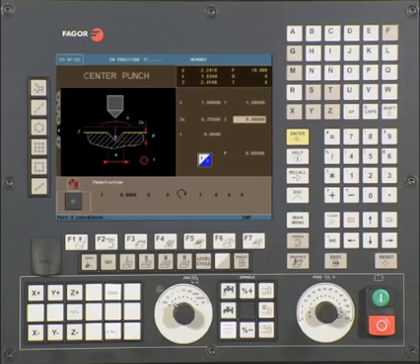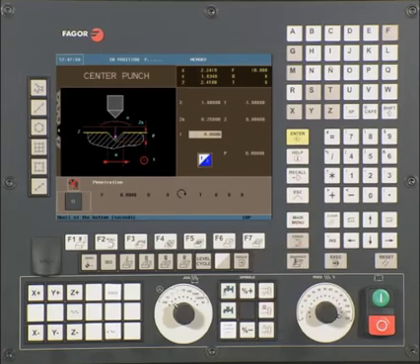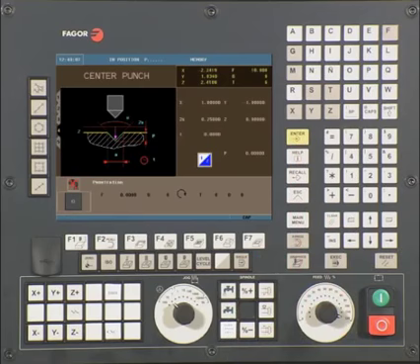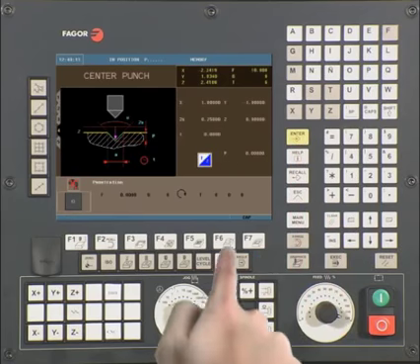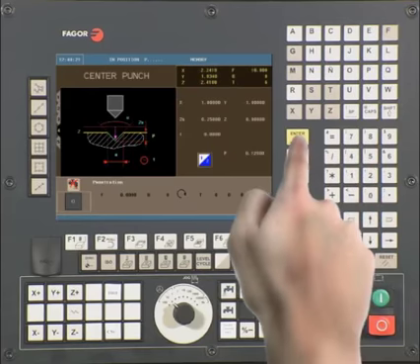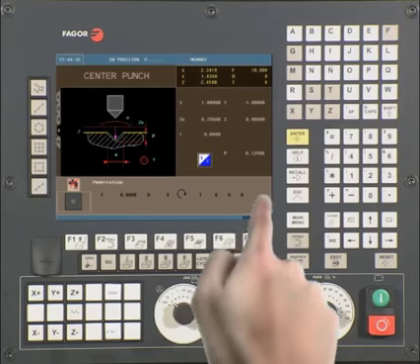Z. This is the starting point on the Z axis. In this example, we will be using a value of 0. Press enter to continue. T is the dwell time at the bottom of the hole. In this case, it is 0. Press enter to continue. Use the 1/2 key to select one of 2 and press enter to continue. P is our total depth. In this case, it is 0.125. Press enter to continue. Use the 1/2 key to select if you want coolant off or coolant on during the machining process. In this case, we will be selecting coolant off. Press enter to continue.